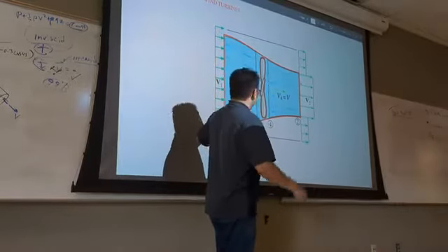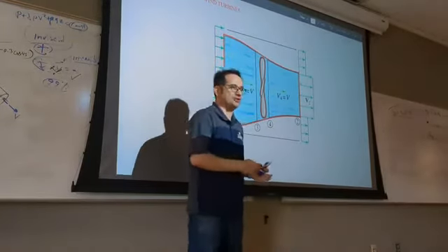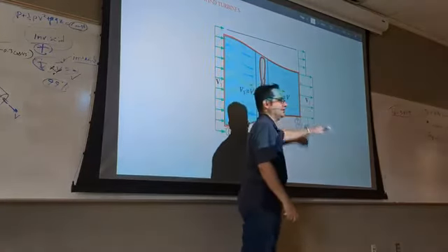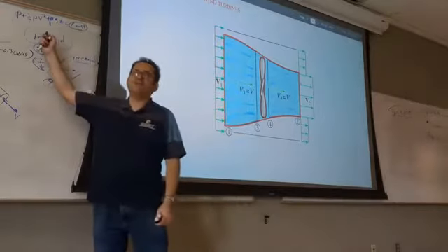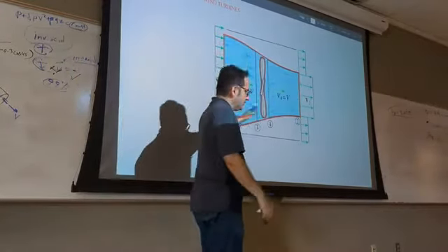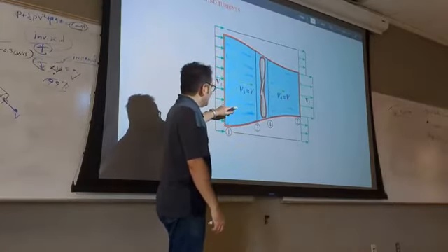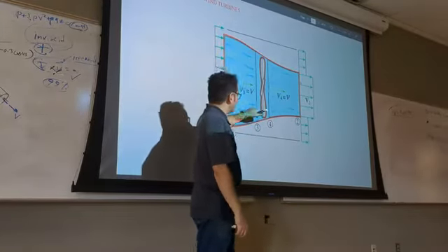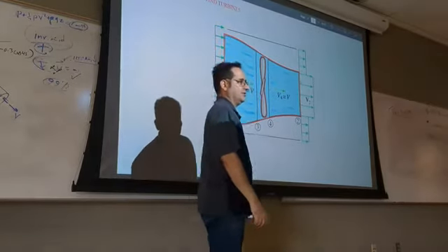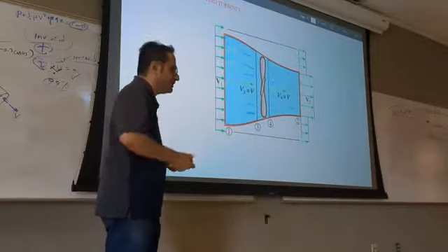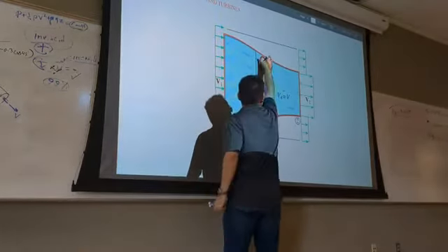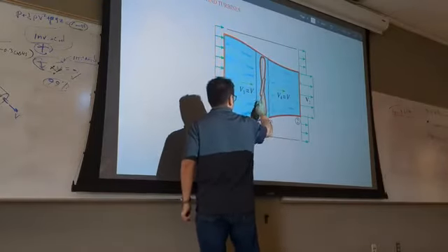So the end result is, I may give conceptual questions like that. Write the Bernoulli equation between this point and this point. When I say Bernoulli, in this course, later on we will add the energy drop and then we can write it. Inviscid, you can't, right? Because there is viscosity here. If there is no viscosity, there is no thrust. There is no way that you can generate thrust. So that's the reason I have one control volume here that is dealing with the viscous effect.